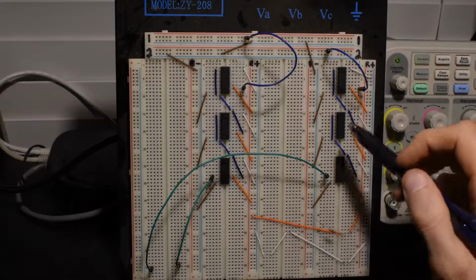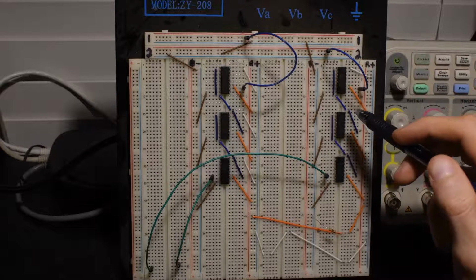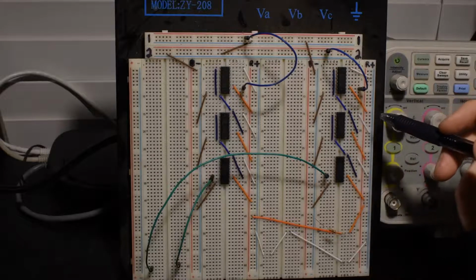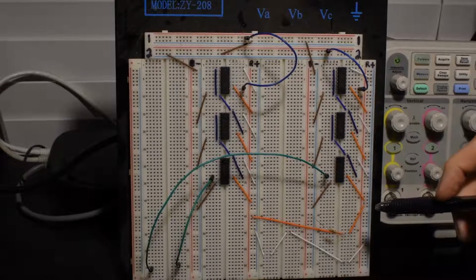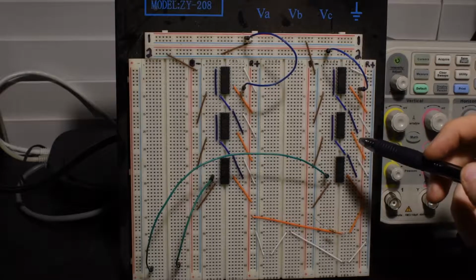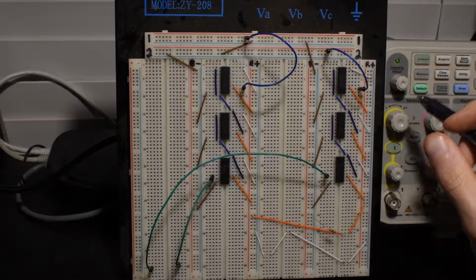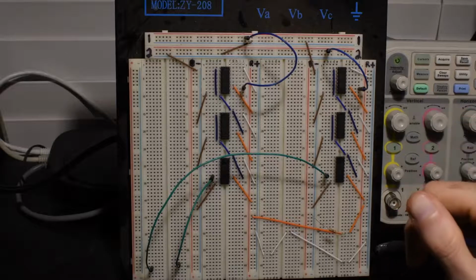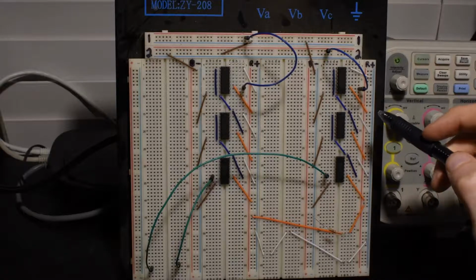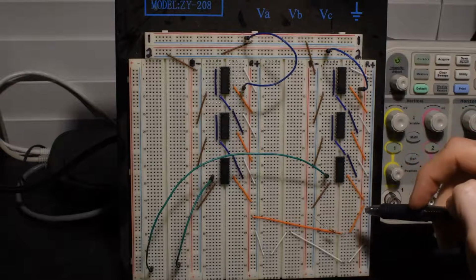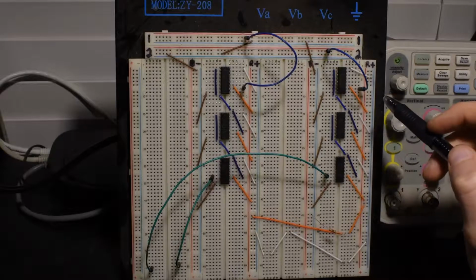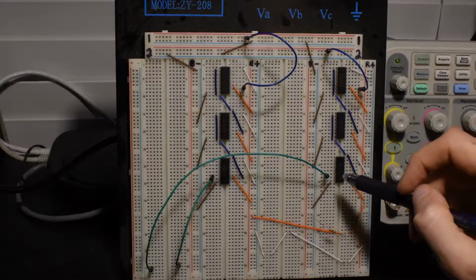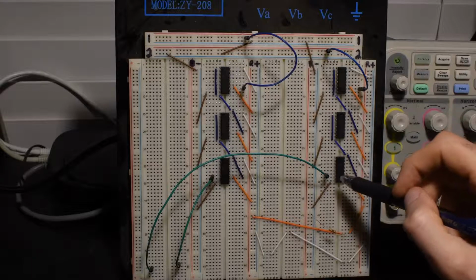So we're not even limited to integer multiples of a clock cycle. We're just limited to the sampling interval of the oscilloscope, so we can measure some really small frequency differences this way, and that's basically how it works.